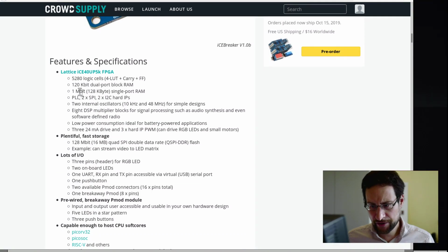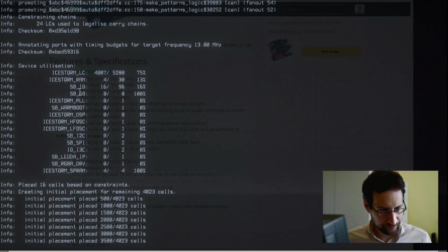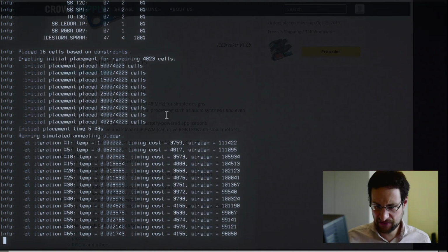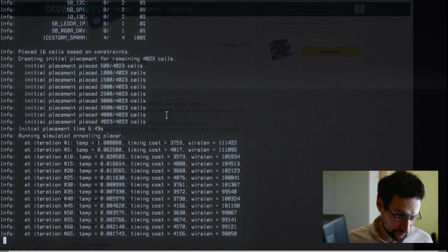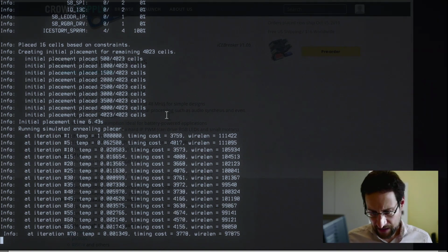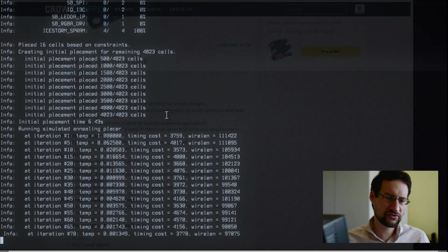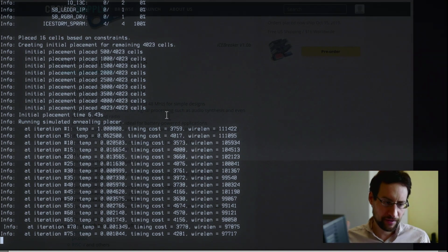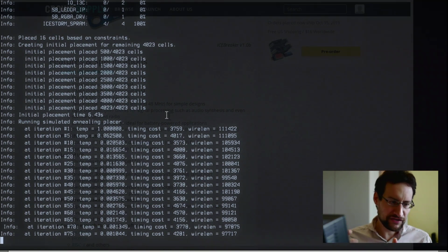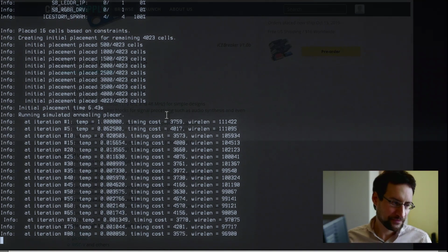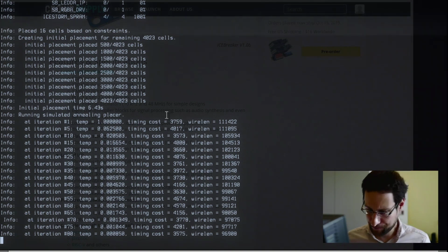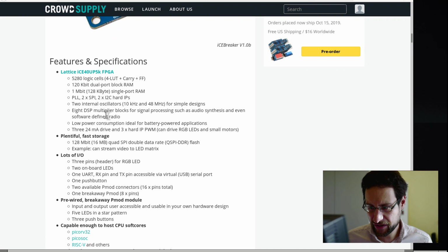So right now, by the way, this is still running. Do we have 28 frames per second? Yeah. You see the synthesis is running quite some iterations to optimize the place and route layout of the interconnects, all the huge tree structure that is the connections of wires between the logic elements. So that's what is going on right now.